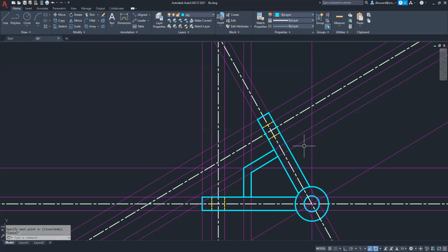But we also have to do this part that sticks out on the outside. How far does it stick out? 1/2 of an inch. So we have to offset 1/2 inch the outer surface of both of these arms. So this line here has got to come out 1/2 inch, and that line there has got to come out 1/2 inch. And that way we know where to make the other bit of this. And it's like that. And it actually goes all the way to tangent here. And then you can make the little line segment there. Same with this one. Click down here, goes all the way to tangent. And then the little line segment there.